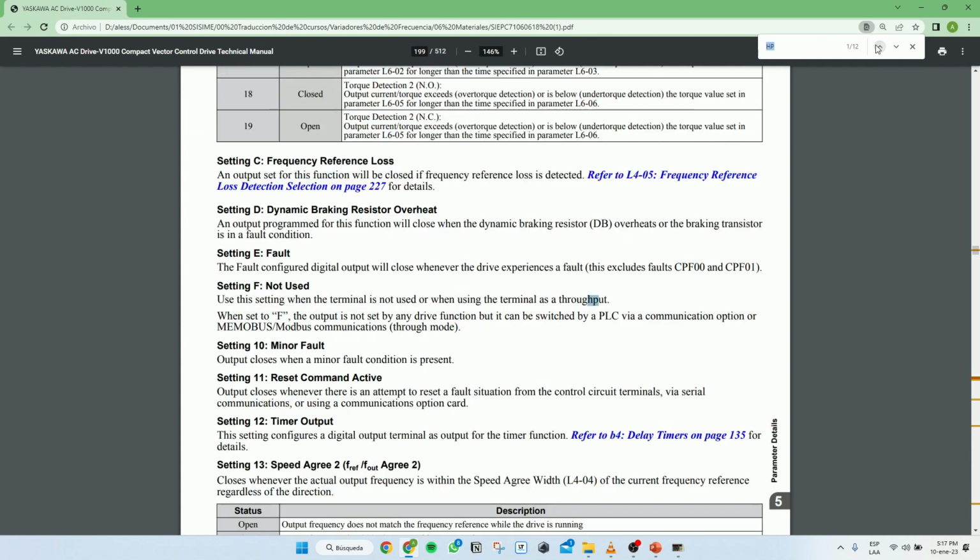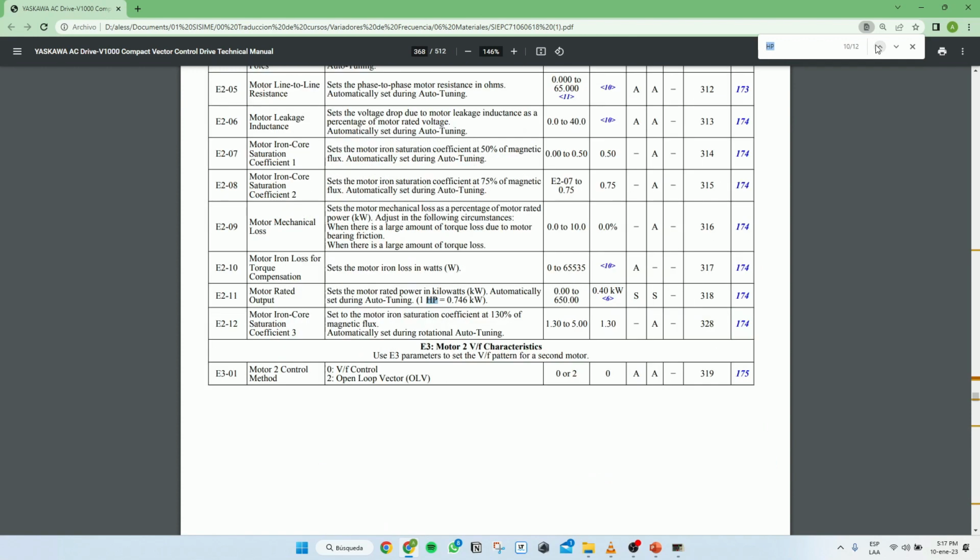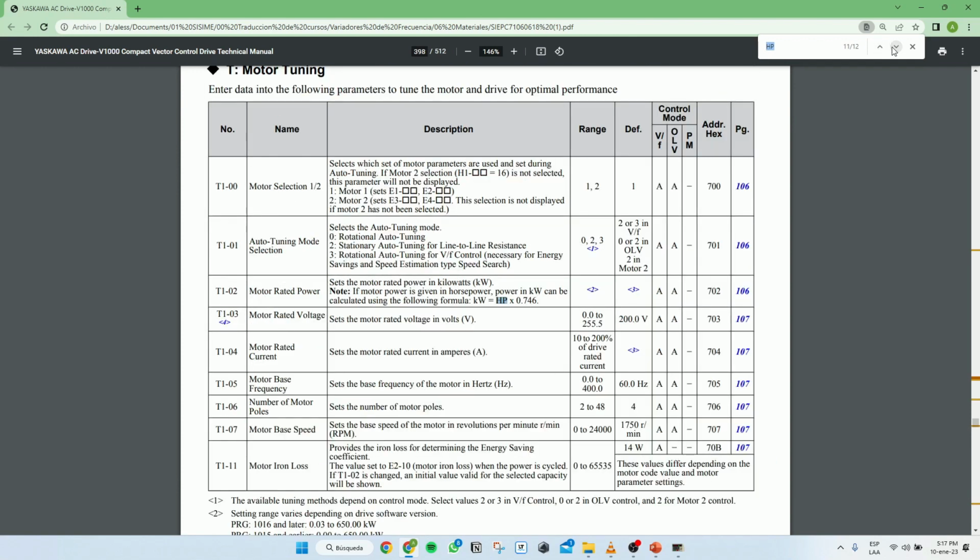So whenever you guys ask for our motor, you need to decide what voltage is going to be used. Quite the contrary, if you're not careful with this and you don't select the voltage for our motor, if you created it with a delta connection and then you said, well, I think it would be better with a bigger voltage with 440, or maybe I should use a star connection.